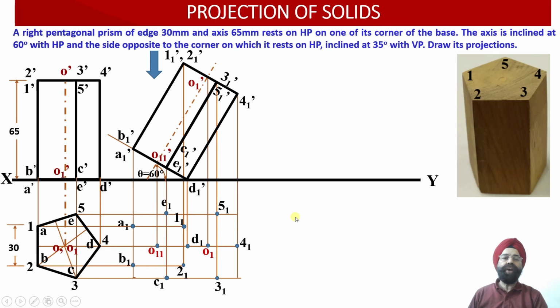But which of these edges have to be joined dark, using the object line? Which of these edges have to be joined using the hidden line, or the dotted line projections, over here? Since the observer is going to look at this object from the top, the farthest point away from the observer happens to be D1 dash. So anything joining D1 in the top view projection has to be joined as a dotted line or a hidden line, unless those edges constitute the boundary of the solid.